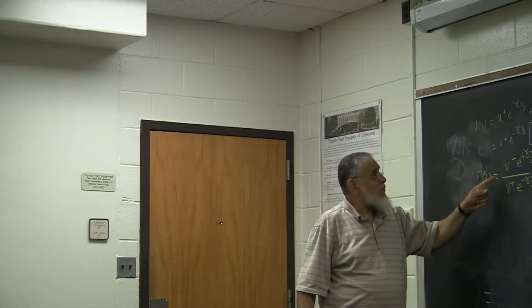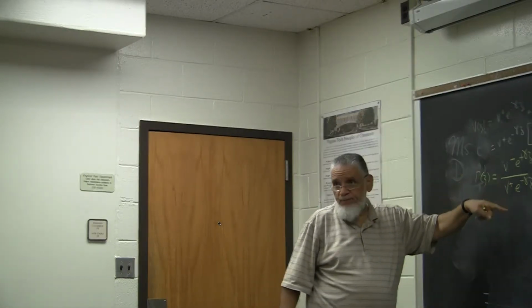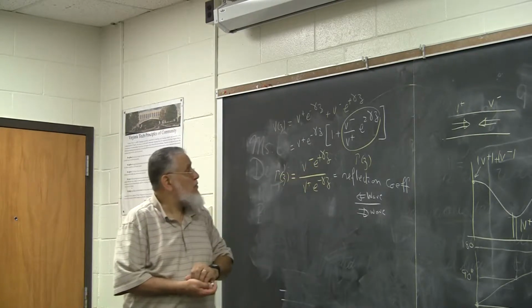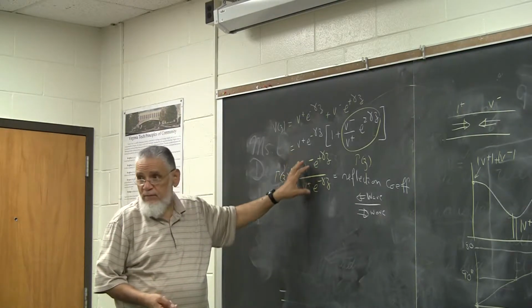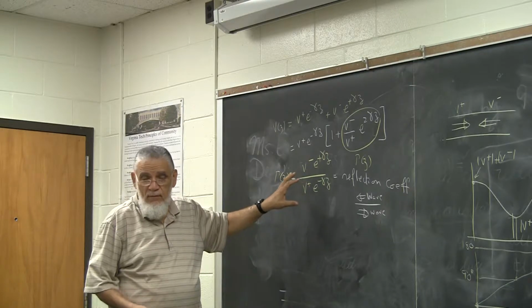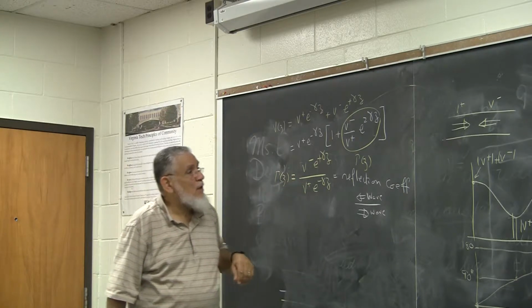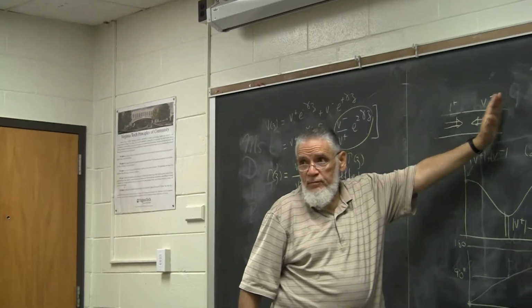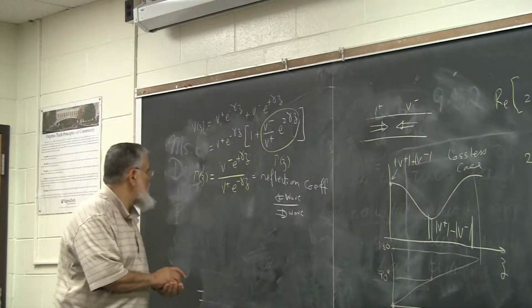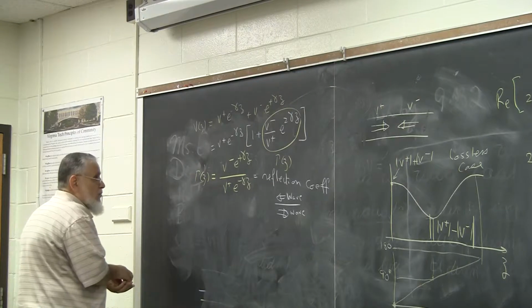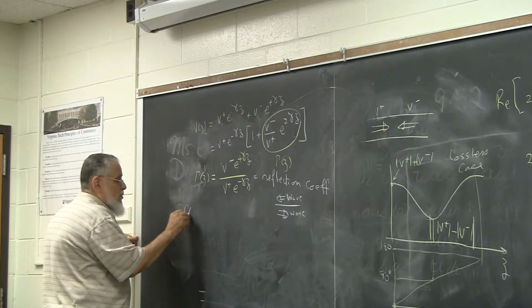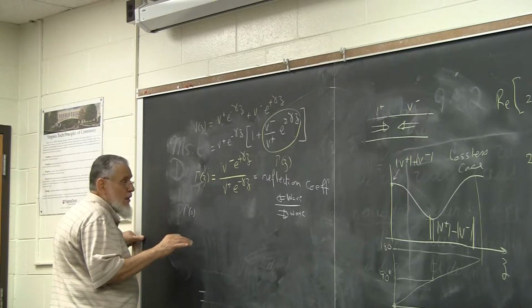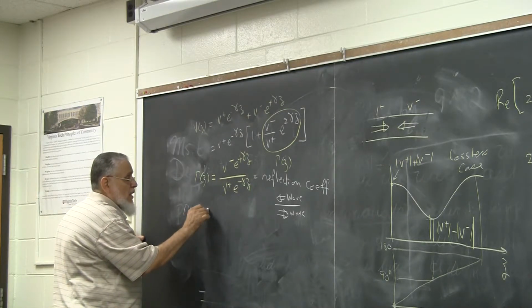It's obvious that that reflection coefficient is a function of position. Right? z is effective. V plus and V minus are constants, right? We mentioned that several times. But different locations will have a different reflection coefficient. So we specify a few locations, gamma of 0, for example, that's the reflection coefficient at the input side of the line, is V minus over V plus.